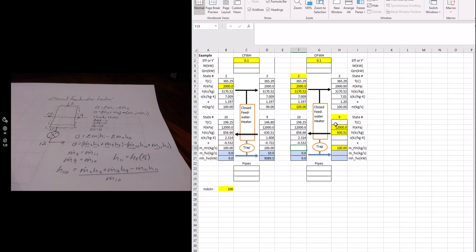So we do the same thing over here, calculate those equations again. So pressure and enthalpy, and I want temperature. Just double check that that's the right cell, so that didn't work. So what I can do is move these over here. Probably safer just to retype them. So pressure, enthalpy, temperature, and this is the pressure, this is the enthalpy.